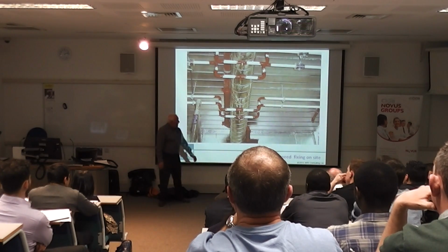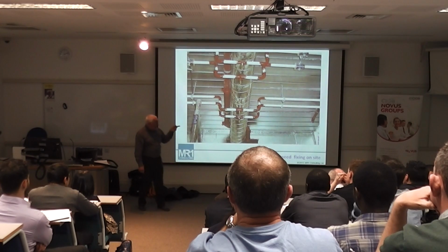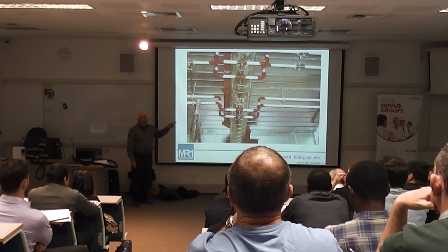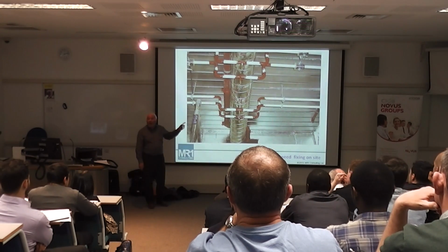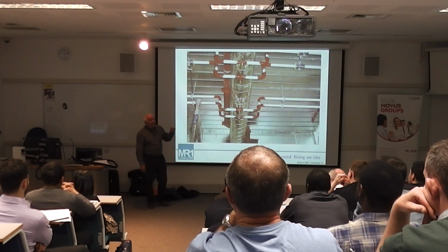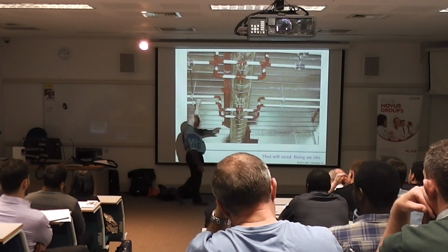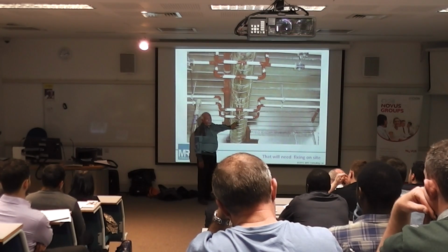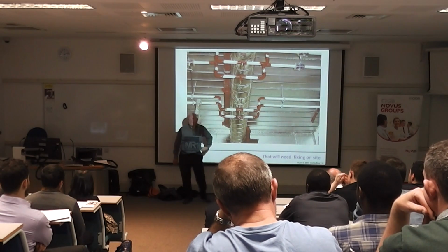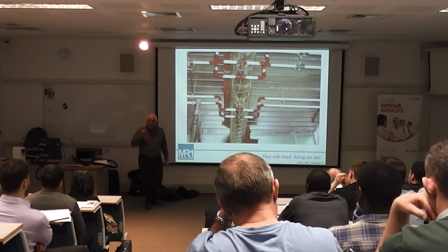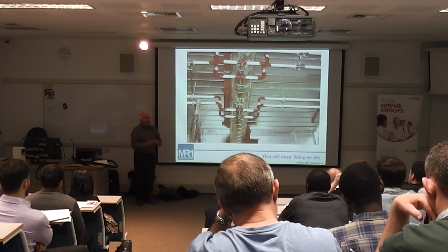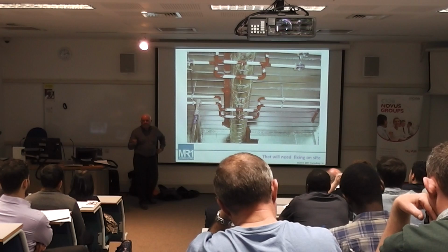Normally, we would see coming out of a construction site with the M&E, around about 50% of the time on site is standing around trying to come up with a solution to the problem. Why did it occur? It occurred because this was only done in 2D, and nobody bothered to check the height of those against the height of that. Checking keeps coming into it. I did not check it. The duct had nothing to do with me. I put my pipe work in, somebody else should move out of my way.